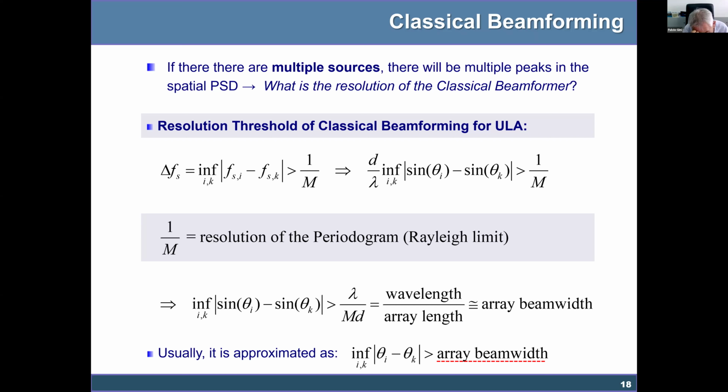So in the estimate of two frequencies, you can estimate them separately if the distance between the two frequencies in the digital domain is greater than the reciprocal of the data size.